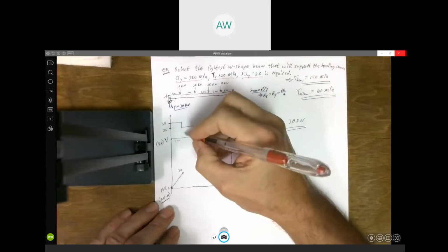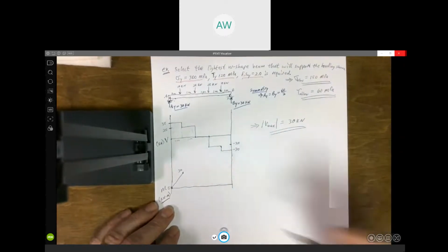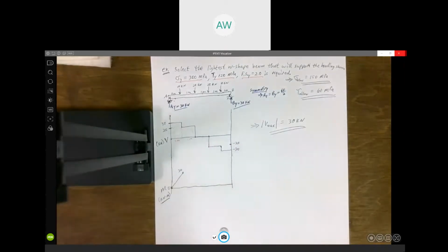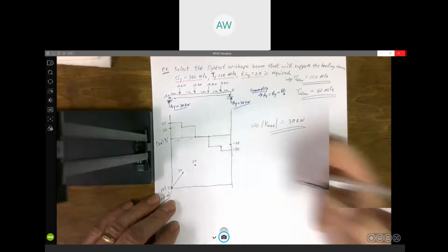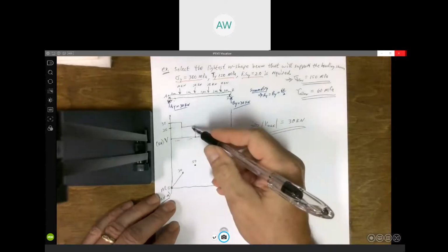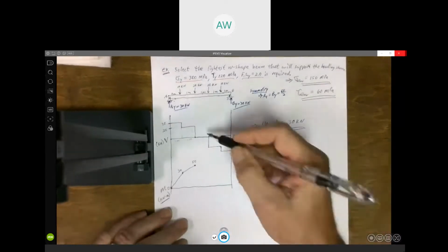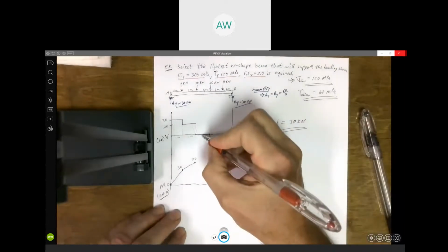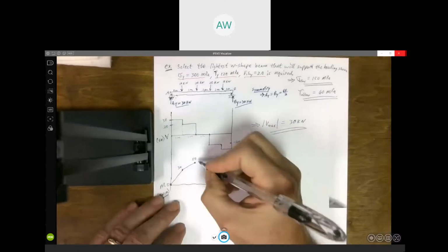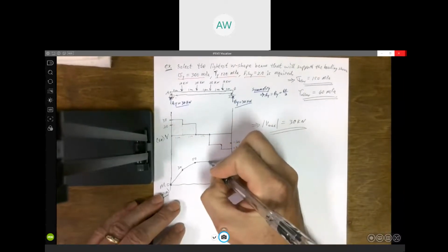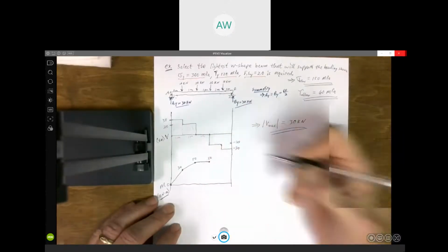Then we're going to go up whatever this area is. Again, the horizontal distance is 1 meter. The height there is 20. So we're going to go up 20. We're going from 30, we go up 20, we're at 50. Constant shear diagram, linear moment diagram. Now here we have 0 area, so it doesn't go up or down. It stays constant, goes straight across. Still at 50. And that looks curved, but that's just me, I can't draw a straight line.